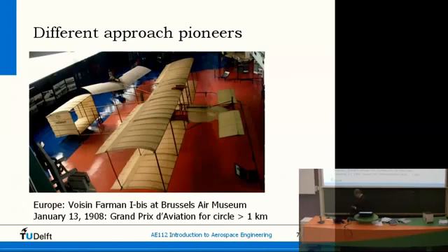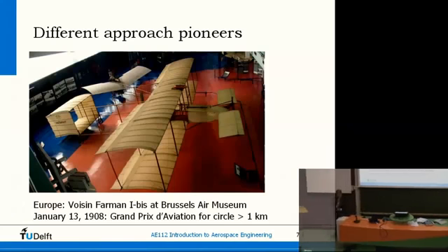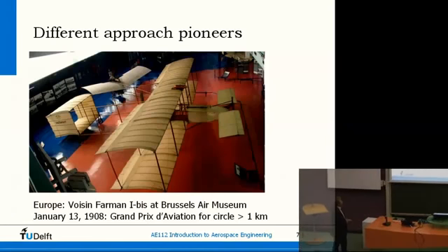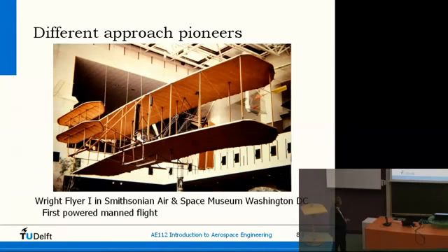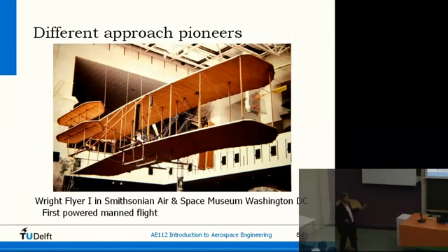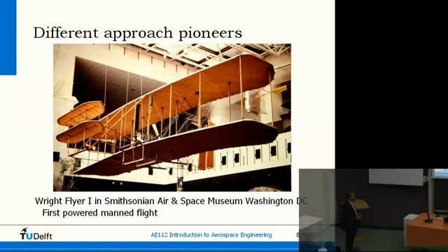to get it around the corner, but not so agile that it would kill you immediately after takeoff. So you see that they moved around the canards and the directional controls and also the ailerons. In this case, you cannot see the ailerons because the Wright Flyer used wing warping as aileron, which means that there is a line somewhere, hard to see. But if you pull on the stick, you would bring down the tip of the wing on the backside, and in this way you would control the aircraft.